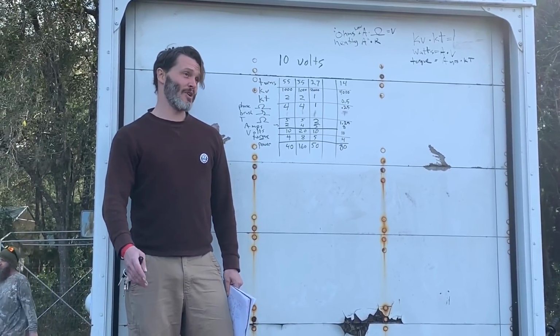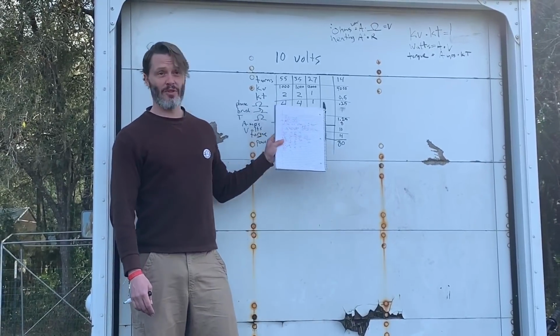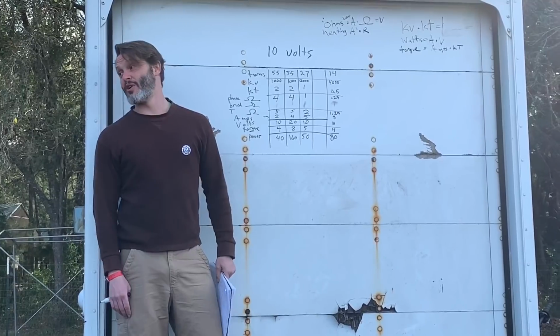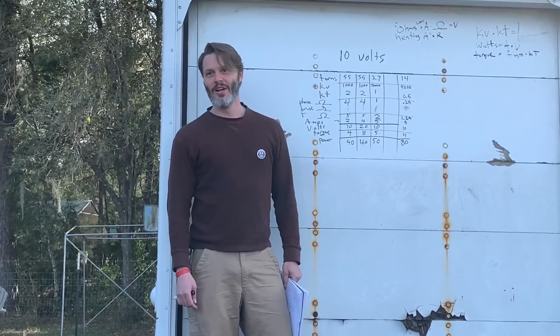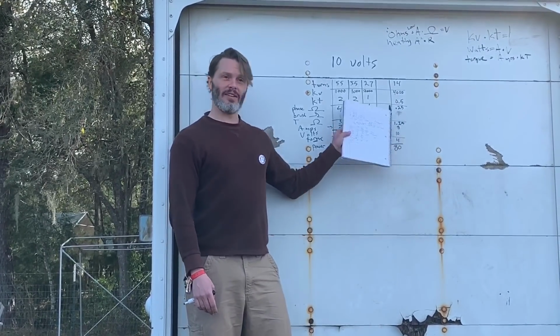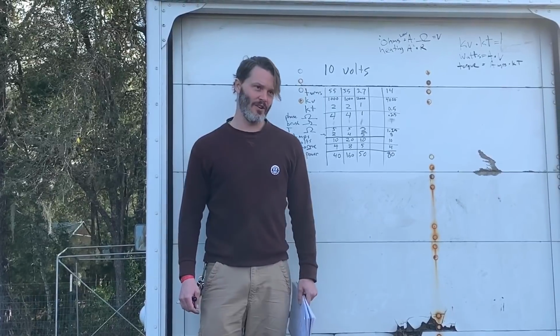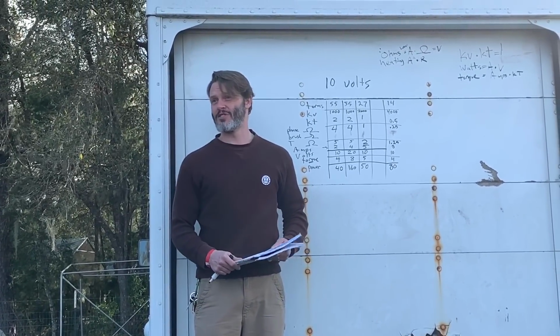And that's my recommendation. If you want brushless, if you want maximum torque in brushless, we're going to be way up here in 3,500 kV. You probably don't need that much wheel speed. You probably don't need that much torque. You don't need that much power, but it is there if you need it. And in reality, most people are going to be down in 2,700 kV, 2,200 kV, or 1,800 kV, and still have all the torque they need, all the power that they need, and still have a system that works.